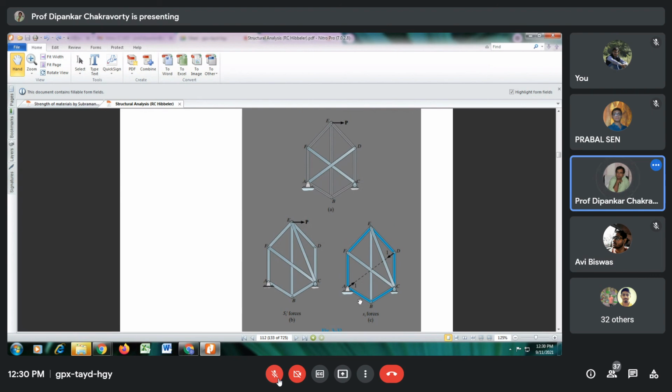You see, any member is a part of a basic triangle. So this is stable. You see, when this becomes a triangle, these 3 joints are stable. So this joint is stable, this joint is stable, this is a support joint. So these 2 members are also stable.